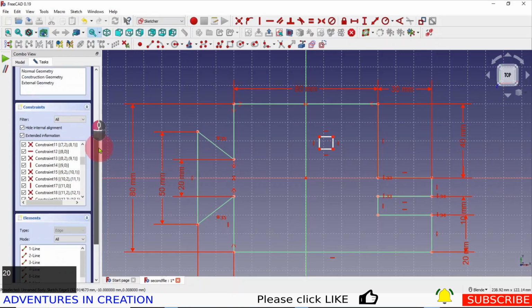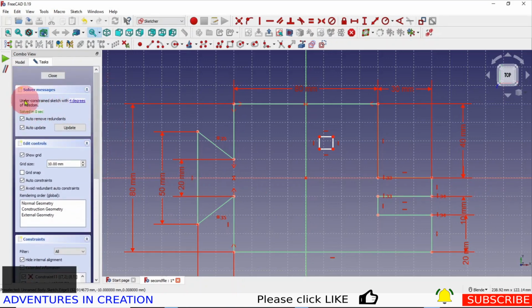And then if I go to the top here, it tells me how many degrees of freedom there are in this sketch. So if I look at this outside shape, I'm just going to click on this line and try and move it. I can tell that this sketch is constrained except for this guy that's still in white in the middle. So first thing I need to do is dimension this square, and this square is a 10 by 10 square. As it's going to be square, I can say this line and this line are equal.